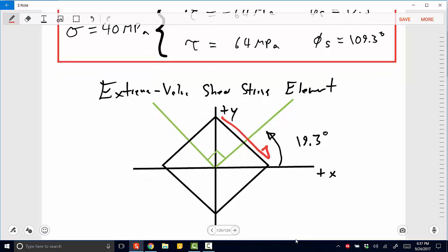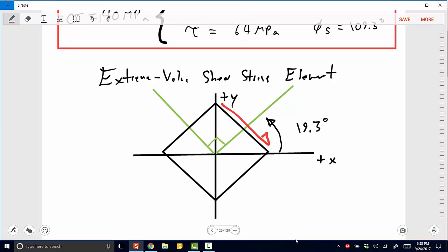So for our element, if we draw our arrow going downwards, it's going to cause a clockwise sense of rotation. So we've got a negative 64 drawn on our body. And from this going downwards, we know to maintain equilibrium, our other side must go up. And if we want to eliminate any sense of rotation, we need a couple moment that is opposite.